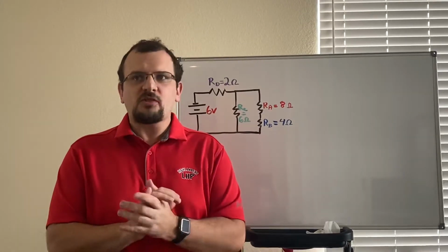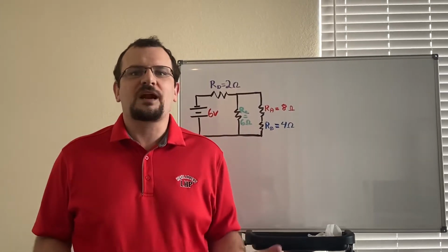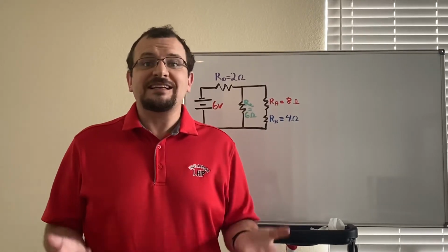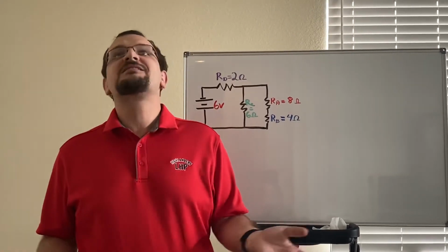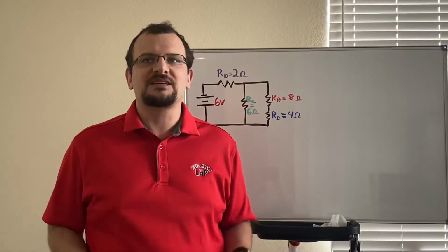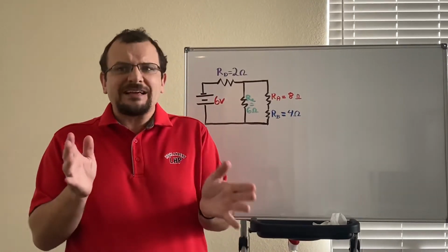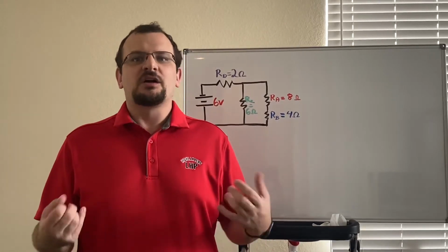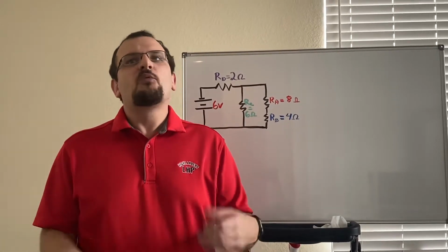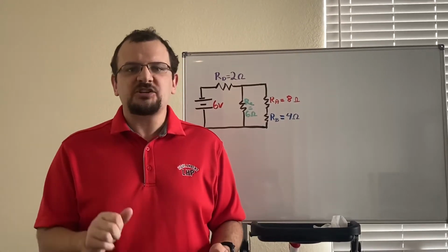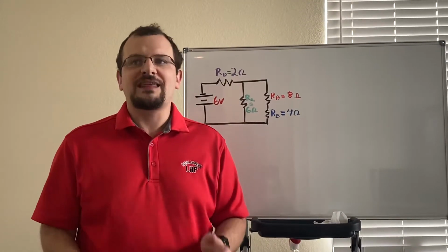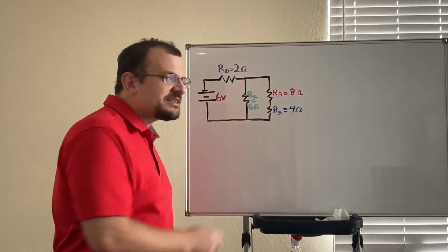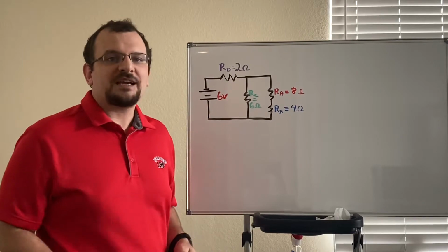For instance, all of the lights around the room that I'm in are wired in parallel because they need that equal access to voltage. In this case, it's the 120 volts that comes out of the wall. However, each one of those lights wired in parallel is then wired in series, current doesn't have a choice, with a switch. That way, when you turn the switch on and off, it operates all the lights in the room. So here's an example of one of these combination circuits.